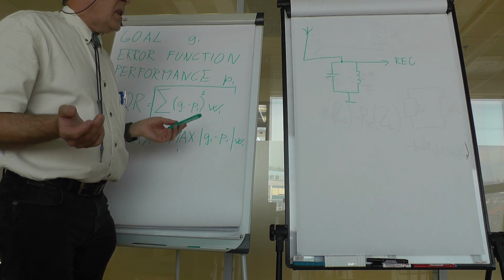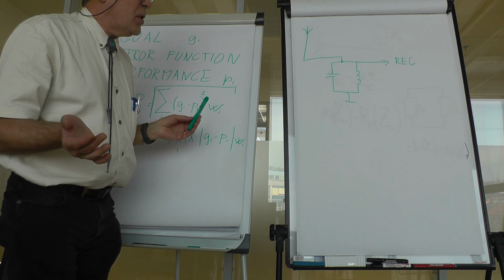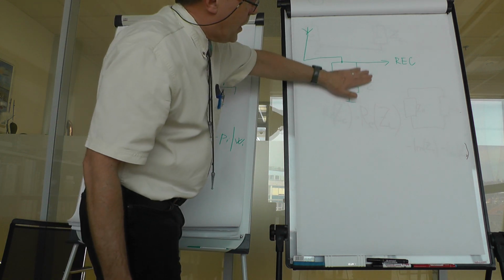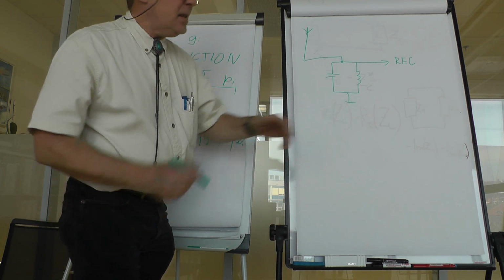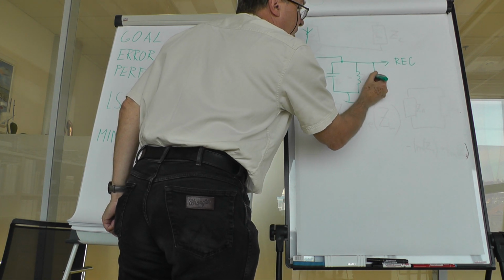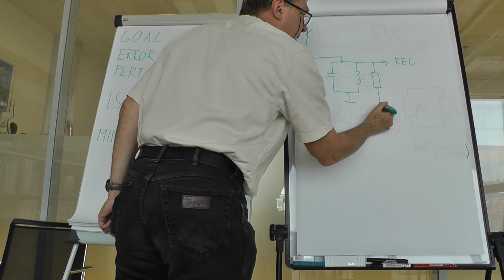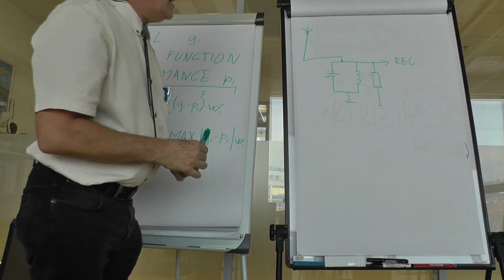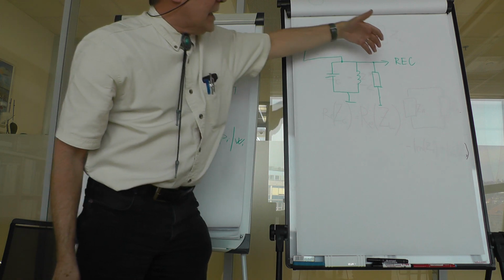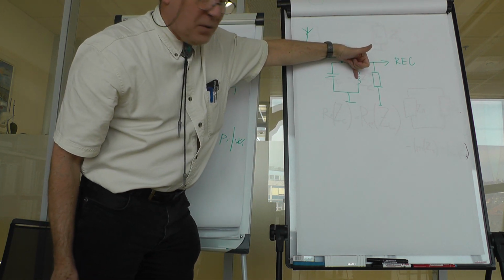Now, you would wish to design the circuit. First, although we have drawn it in this ideal case, it's not true. The receiver has some input impedance. If it has a capacitive part, it adds to the capacity. If it has an inductive part, it adds to the inductor.